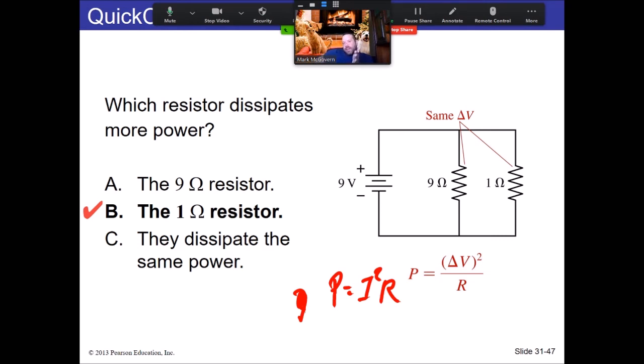In fact, in this setup here, I said proportionally. And what's going to happen is the current that flows through the right-hand side is going to be 9 times larger than the current on the left-hand side of the two resistors here, right? That's Ohm's law, right? Delta V equals I times R. They have the same delta V's. So if one has 9 times the resistance, then the other one pulls 9 times the current.